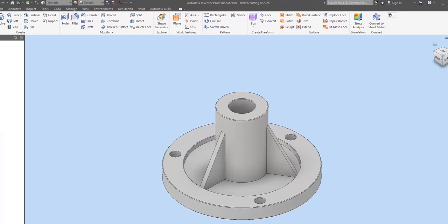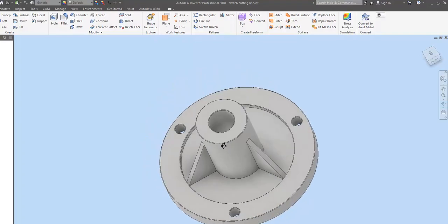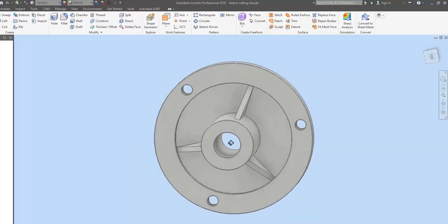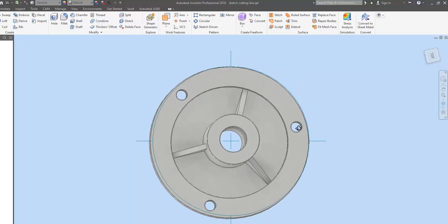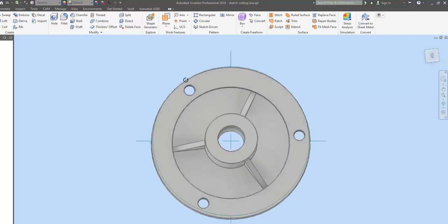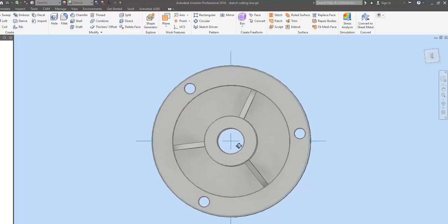Now, say here, there is a revolved body with some features. If this rib, for instance, is directed as parallel to the picture plane, then the others are going to be inclined. If the radial axis of this hole, for instance, is directed as parallel to the picture plane, then those of the others are going to be inclined. So note that for this body, aligned sectional is the case, and see how it can be created.